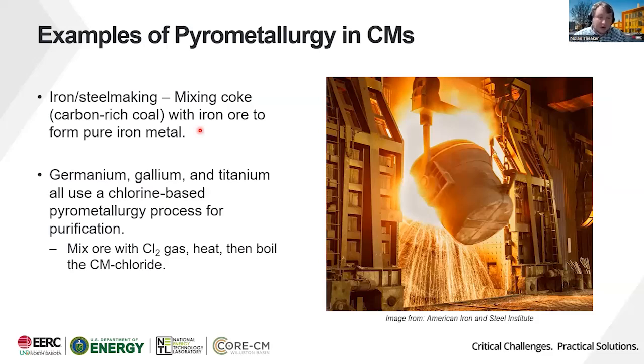And for critical minerals, germanium, gallium, and titanium, I'll use a chlorine-based pyrometallurgy process where I'll, in essence, mix just the rocks with chlorine gas, heat it, and then boil off the critical mineral chloride, and I'll eventually get my pure critical mineral that way.